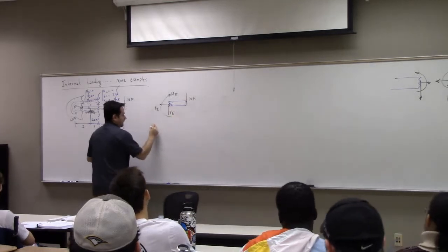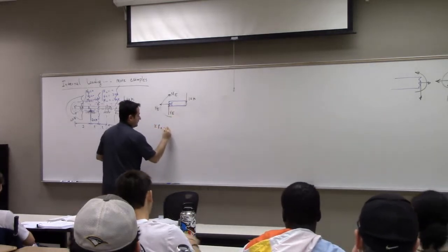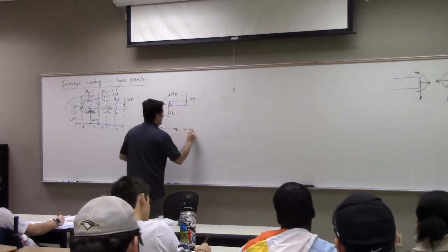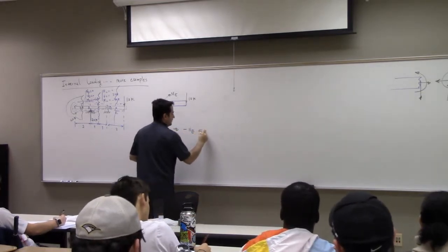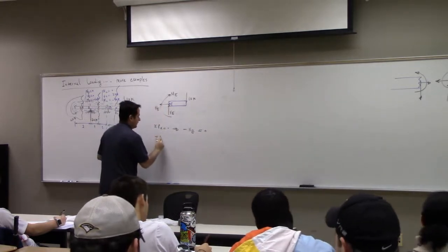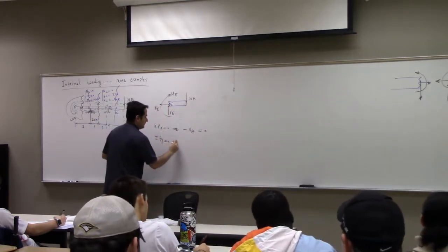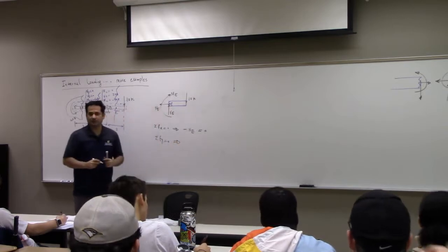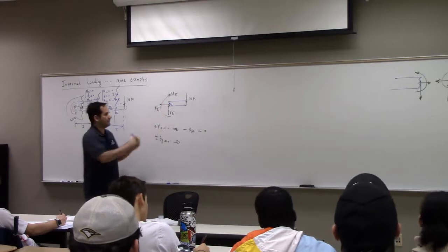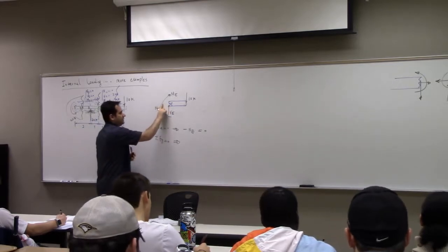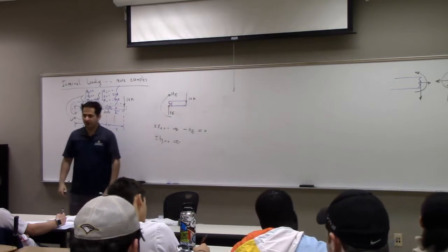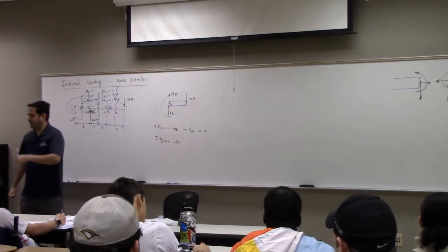So here, again, summation of force in X, 0. What do we get? Negative NE, 0. Summation of force Y, 0. And later, when you do more practice, you immediately just don't do a lot of extra work. For example, you can just simply not include this on your FBD because you know it's already 0, right? You can save a lot of time later on when you practice.